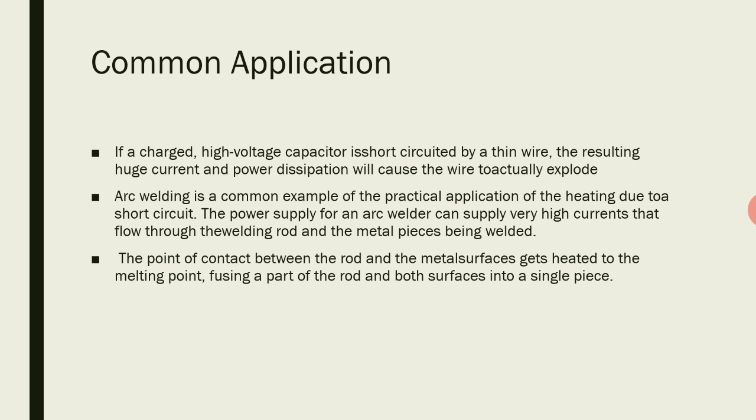Although short circuit is considered a bad thing, it has some useful common applications too. One of them is arc welding. If a charged high voltage capacitor is short circuited by a thin wire, the resulting huge current and power dissipation will cause the wire to actually explode. The power supply for an arc welder can supply very high currents that flow through the welding rod and the metal pieces being welded. The point of contact between the rod and the metal surfaces gets heated to the melting point, fusing a part of the rod and both surfaces into a single piece.